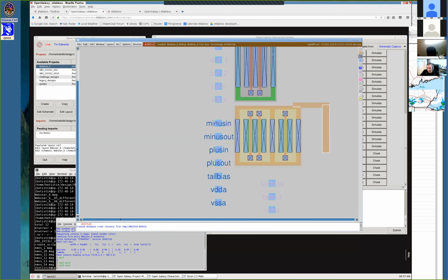Normally, you'll probably want to do the contact instead of just the diffusion layer, and then connect up to your VSSA bus, say, by drawing the metal lines. So I think that covers pretty much everything you need to know in order to get started with the layout. And so at this point, I'll open it up to any kinds of questions you might have.